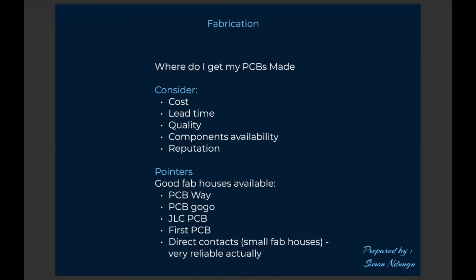Are the components available at the fab house? This applies in terms of region, or where you want to get your PCB done. If you get your PCB done locally, are the components available for you here? Are they going to be able to do the assembly here, or will they also start shipping components from outside? So it's good to check the availability. If you get one done in Europe or maybe in the USA or China, what is the best option in terms of component availability?